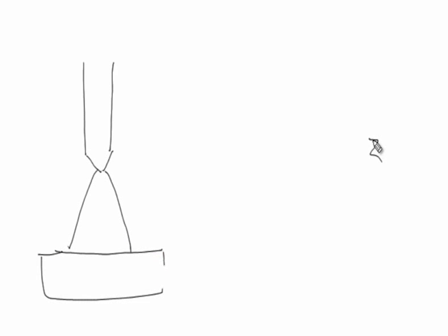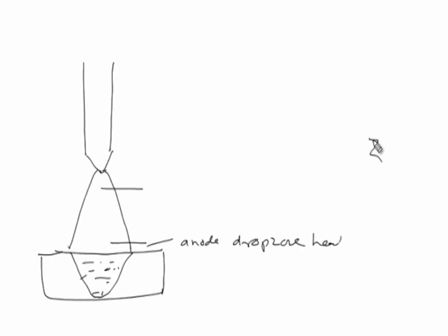To understand this, if we see here, there is a non consumable arc welding process where the electrode does not melt. The arc is established between the electrode and workpiece, where the workpiece melts because of the heat of the welding arc, but the electrode does not melt because of its non consumable nature. The heat is generated in the same way in 3 different zones, that is the anode drop zone, heat in the plasma zone,